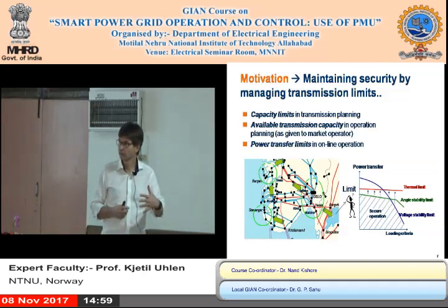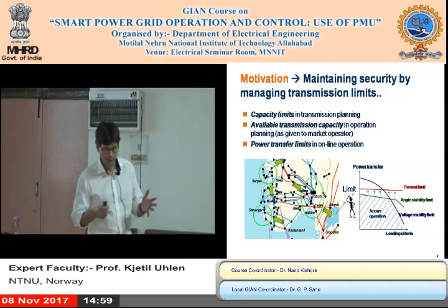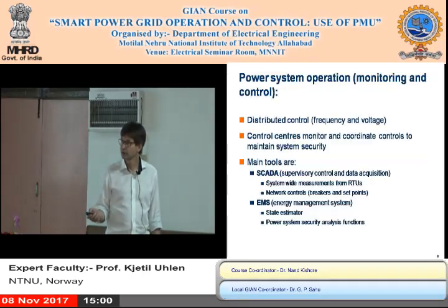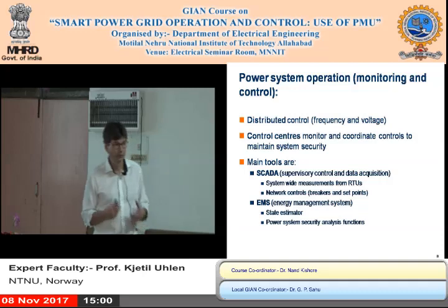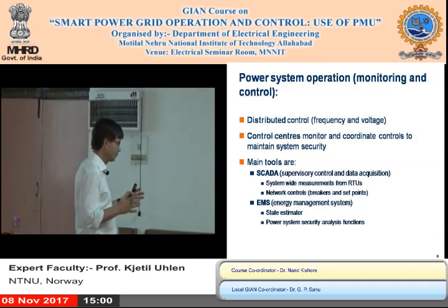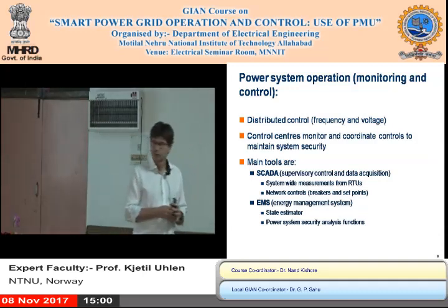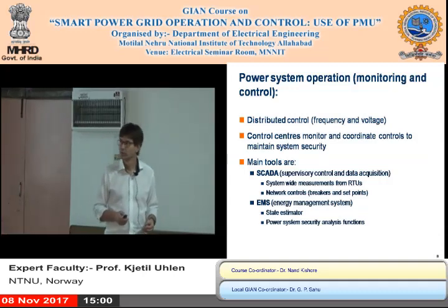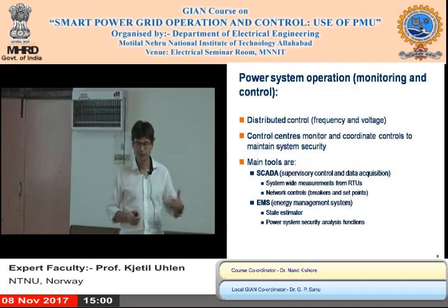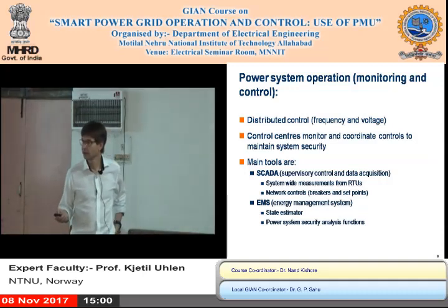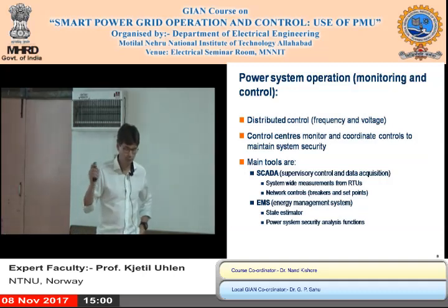And the background for this, as I have been touching upon, is that traditional SCADA EMS is rather slow. It's focused on steady state. You have updates with different sampling rates, could be from minutes down to maybe 1 second or something. But it's not synchronized, and the measurements come in when they're available. So it must have focus on the steady state. But as we have seen, the power dynamics can be much faster than 1 second.